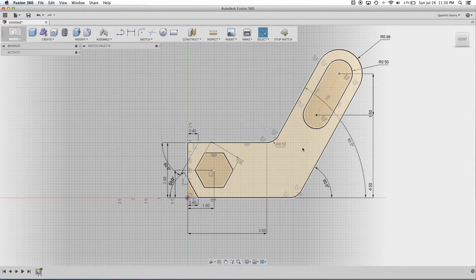All right. Next up, we're gonna go ahead and extrude this, and to do that is pretty simple. You got to make sure you have an enclosed surface or an enclosed sketch. So if you notice what's being highlighted here, that's the part that I want to extrude, and anything not highlighted is obviously not going to be extruded.